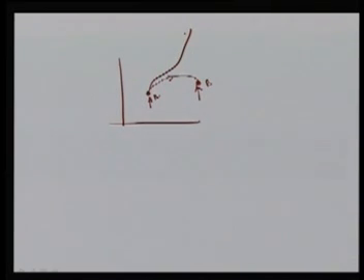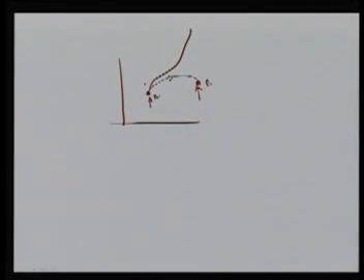We know that this is your pre-fault condition, the initial normal condition where your system is operating. If there is any disturbance, then your system should go to another stable point B. B may be different, again it depends upon the system scenario, change in the topology, change in the generation and the load scenario. It may be the same point A, of course, but after the disturbance is cleared, your system must go to another stable point B, then we can say the system is stable if it is coming to this point here through any region.